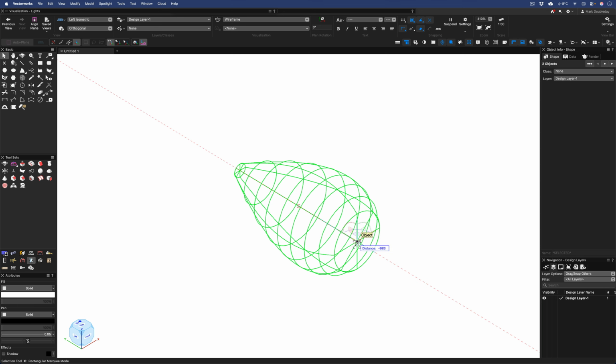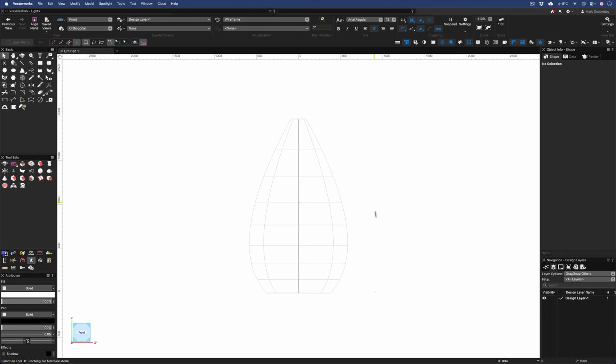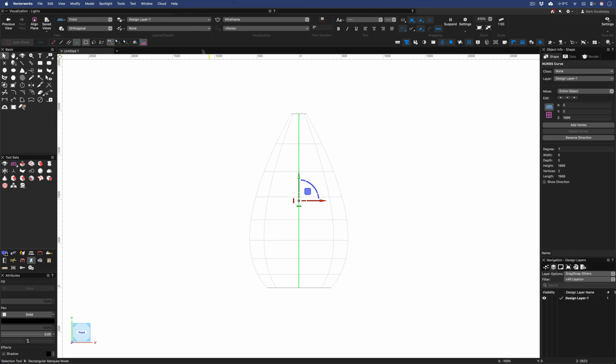a 3D dragger, I'm just going to rotate them up to a normal orientation so I can look at this now from the front. So taking the NURBS curve, I'm going to use the helix spiral command, which is from the 3D Power Pack.